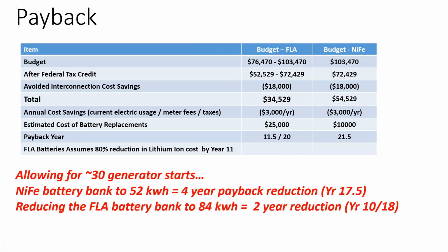And that was for a system that didn't really rely upon the generator for anything more than to make sure it ran its maintenance cycles. And then it turns out that we really didn't even need the generator for the maintenance cycles. What we didn't know at the time was if we would be able to get enough power output from our array to power the maintenance cycle during the day. As long as you're running your maintenance cycles on a sunny day with no clouds in the sky, you can run the lead acid maintenance with the solar array itself.